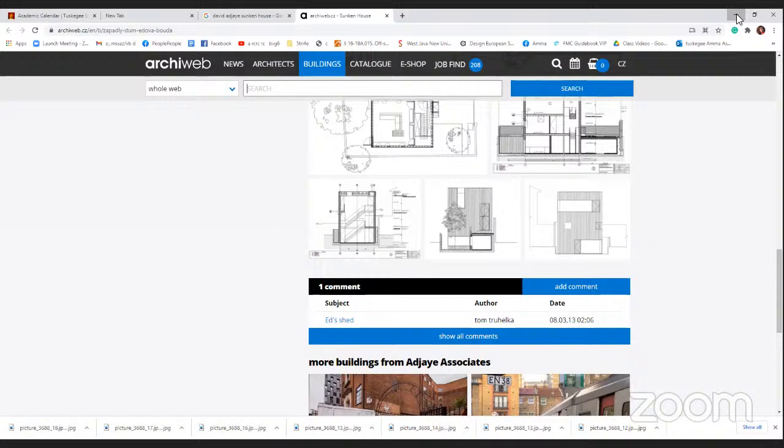So here we are in the AutoCAD model space. You can tell it's in 2D because you got that XY axis here. You can change it to different viewports so that you can see things in 3 dimensions. You can also open multiple viewports in model space, like basically divide up the window so that you can see it from different views. But since we're just working on 2D documents, it's not necessary to do that.